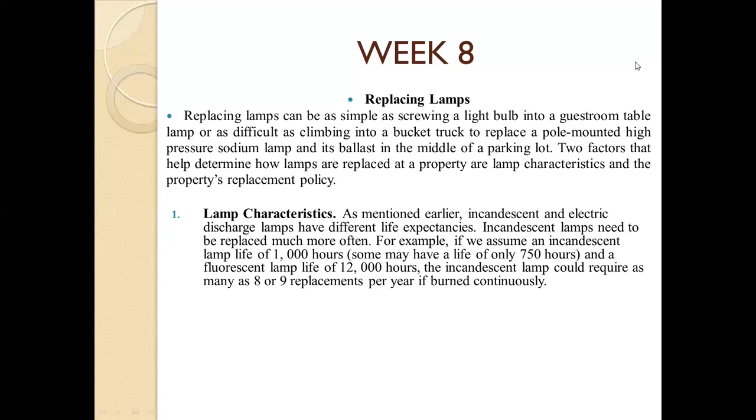For example, if we assume an incandescent life of 1000 hours, some may only have 750 hours. So you must establish a replacement program right ahead for areas which have incandescent lamps.